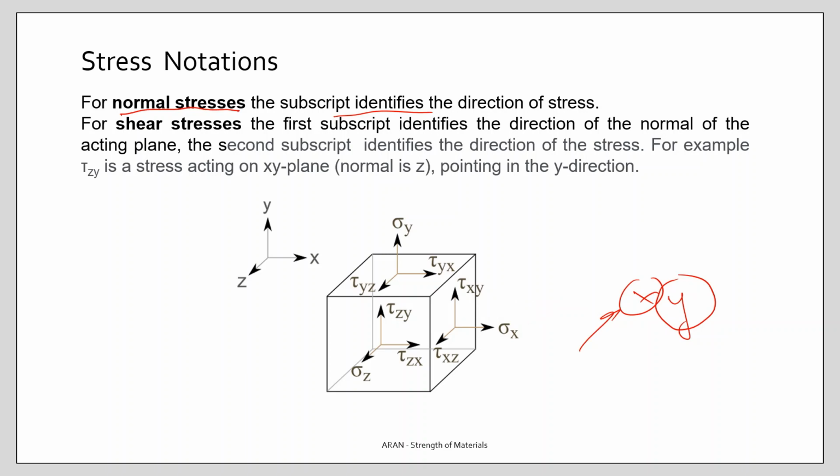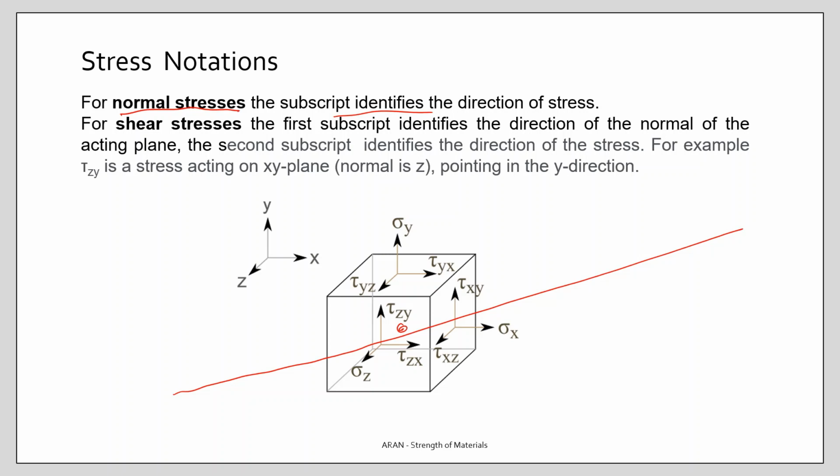In order to be able to calculate the shear and normal stresses on a plane going through this point, well, this plane may have any angle. There are infinite number of planes going through this point. If we know these 9 components, then we can calculate the shear stresses and the normal stresses on any plane, and we can say that we know the stress state in this point.